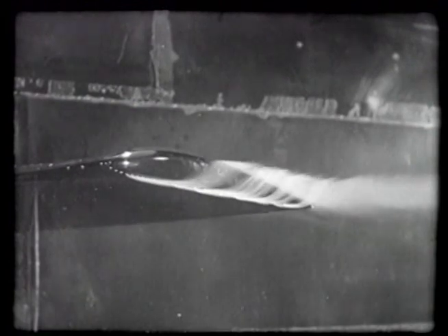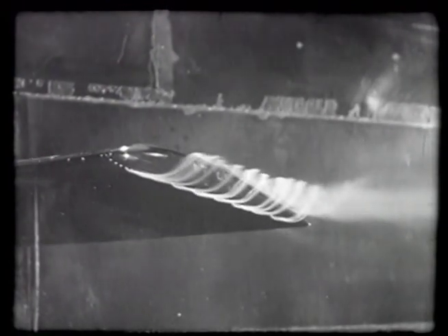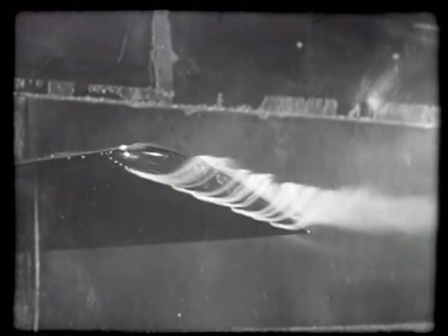Now we increase the angle of attack, and at once the rotational motion around the tip starts, and you see very distinct these particular flow lines, which now spool up all into kind of a rope, which forms this vortex, which starts from the upper part of the wing tip.